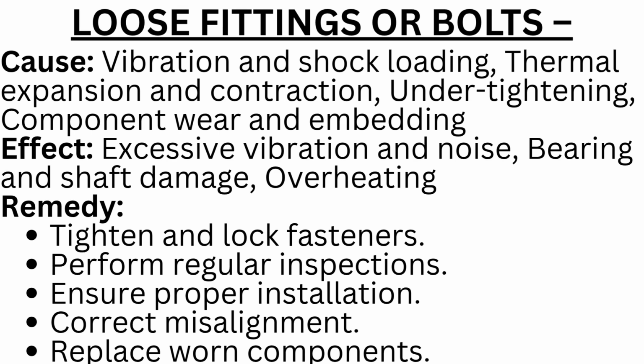The next mechanical failure that we will look at is loose fittings or bolts. Cause: vibration and shock loading, thermal expansion and contraction, under tightening, component wear and embedding. Effect: excessive vibration and noise, bearing and shaft damage, overheating. Remedy: tighten and lock fasteners. Perform regular inspections. Ensure proper installation. Correct misalignment. Replace worn components.